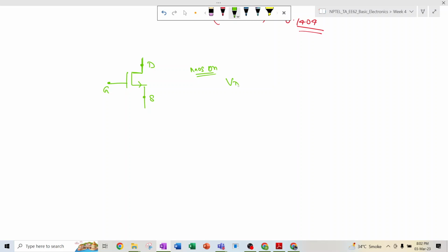Okay, actually I want to discuss one thing. You are not aware of the MOSFET. Basically, suppose this is a MOSFET, it is similar to the BJT. Instead of base we call it gate, instead of emitter it is source, and instead of collector we call it drain. The MOS is in active region when VDS is greater than VGS minus VTH, otherwise it is in the triode region.